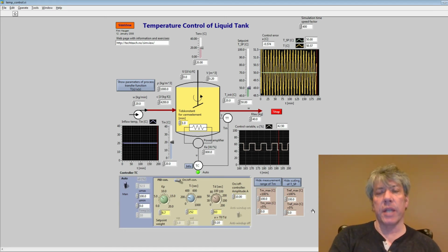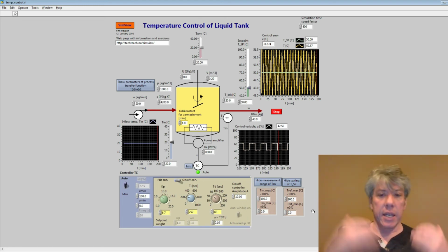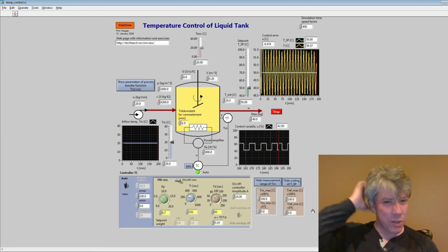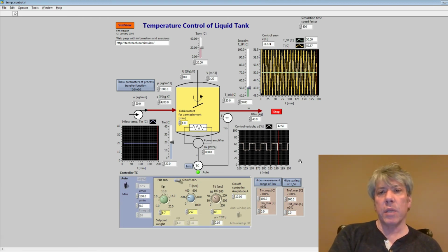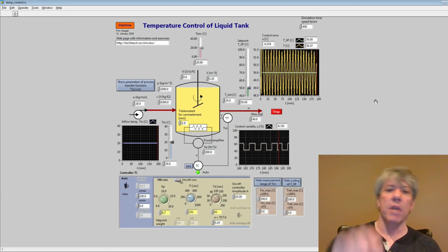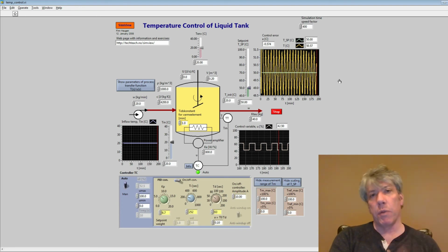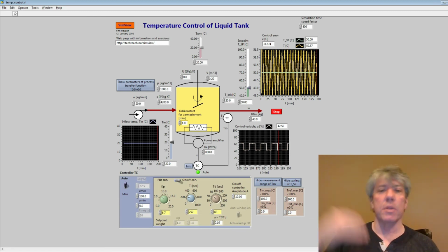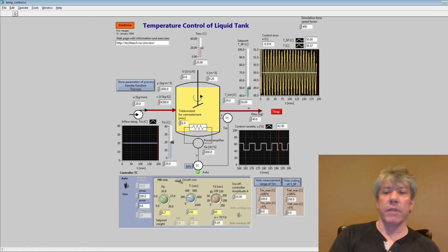So they're scaled the same way so that a temperature of 0 degrees will come in as a 0% signal, and a temperature of 100 degrees comes in as 100% signal. This can be a little confusing at first because the numbers match a little too well. But basically what that means is that if I'm getting a signal of 48.5 degrees Celsius and 51.5 degrees Celsius, then the temperature transmitter is giving me a signal minimum 48.5% and maximum 51.5%, which makes the math pretty easy, because to get the error response I need the difference between 50% and 51.5%, which is 1.5%. So because this is set up so nicely with these scalings set so that 0% is 0 degrees Celsius and 100% is 100 degrees Celsius, it makes our life very, very easy.